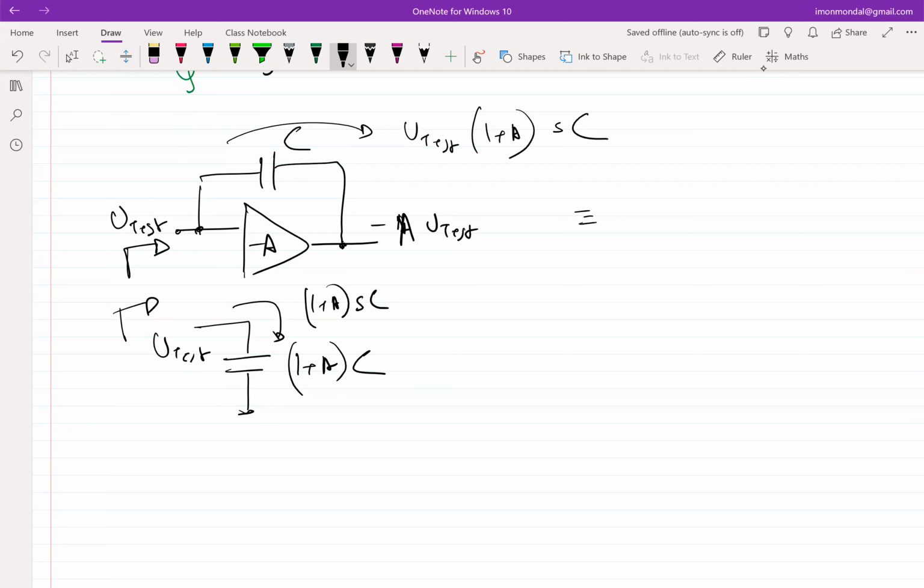So this is one of the ways you can trick the system into thinking that you have a large capacitance. But the problem is very apparent: the voltage controlled voltage source of gain A. That's what we were after. Anyways, the question now is, what does a voltage source mean? A voltage source means that even if I don't have this C, if I put a voltage V, I should get minus A times V.